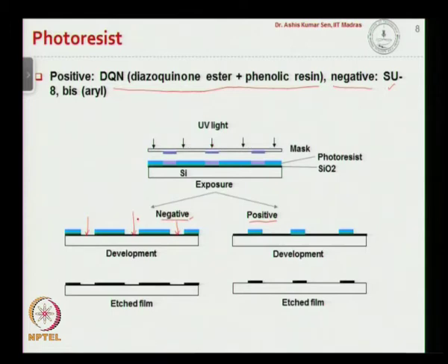So, here in these unexposed areas where the mask is protecting the UV light are going to be removed from the wafer. So, then subsequently let us say we have another film underneath, let us say an oxidation layer which is denoted by this black line. Once the photoresist is developed, we use this layer as a protective mask for etching silicon dioxide. So, this is the etched film that we get, okay, starting from here.